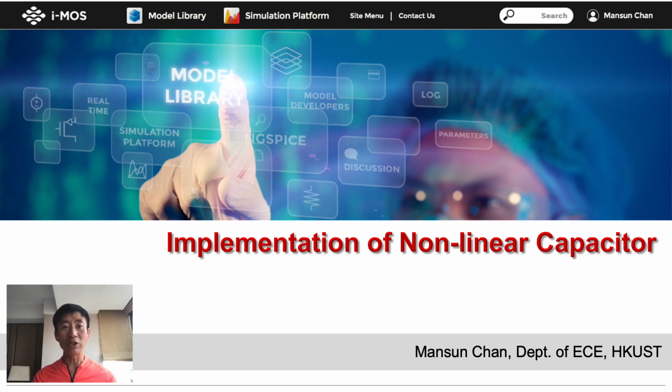After going through the numerical details in time domain simulations, we can discuss the implementation of nonlinear capacitors. It does not look as straightforward as it is supposed to be, and earlier implementations had led to the charge non-conservation problems. The problem is quite well known today. Reviewing what causes the problem can provide us with insights on the interaction between the models and the circuit simulators. Such knowledge will help us to avoid some obvious mistakes in the future.